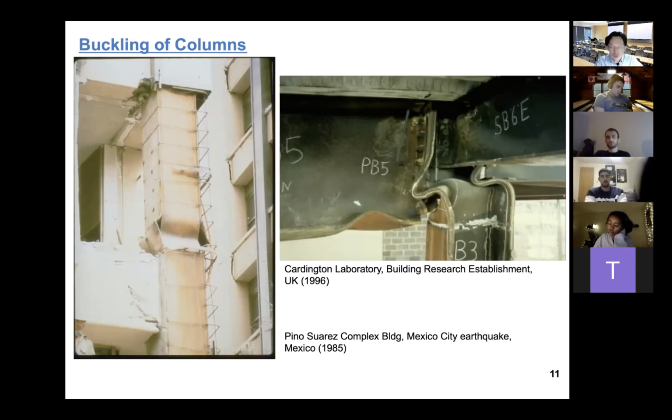You certainly know we can do it, right? I can create two different cross-sections. One is a hollow, the other is an I-beam. And they all have the same value of moment of inertia. Would you agree? Is it possible? Of course it's possible. But when it comes to buckling, they may give you totally different modes. They will look totally different.